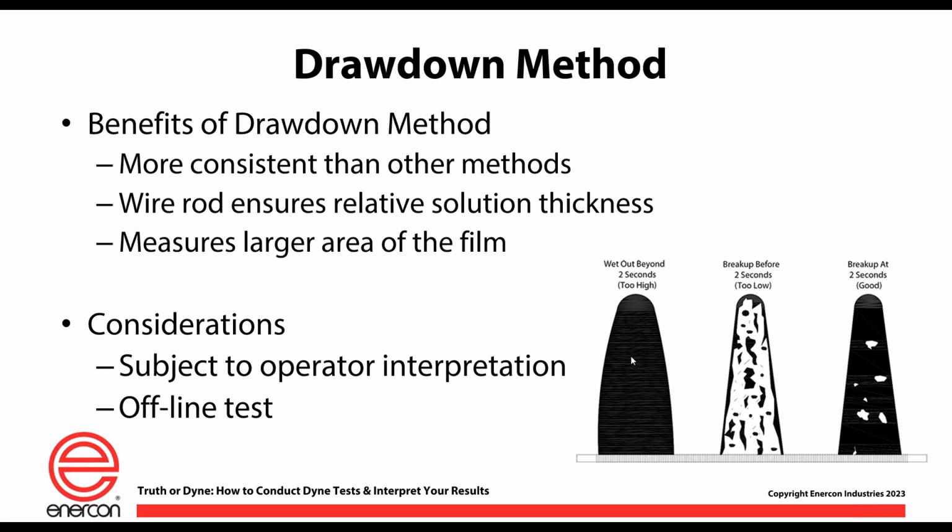If you use a Dyne pen or even the cotton tip swab, the amount of Dyne solution you're looking at is like 1/8 of an inch or 1/16, maybe if you're lucky, 1/4 of an inch. Hard to read, right? It's hard to be consistent by just using those methods. So I like those previous methods simply to determine what side of the film has been treated.